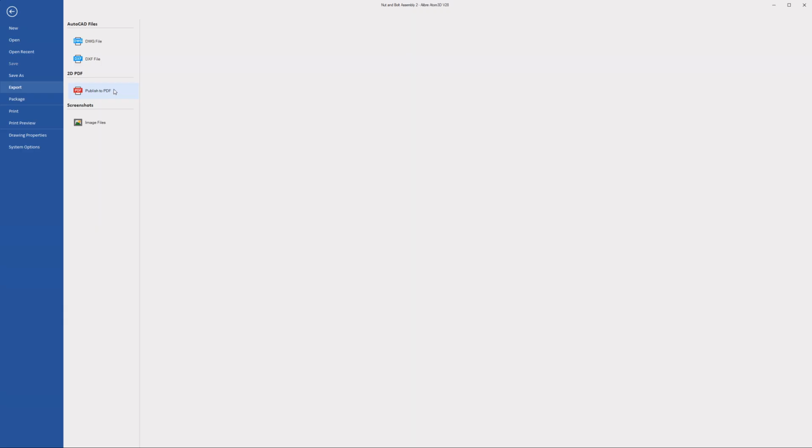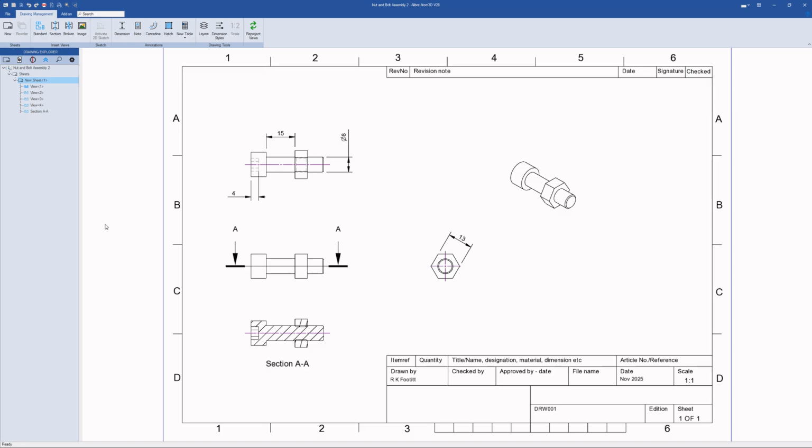However, if you're looking for a 2D view that can be manufactured against, then we also have options for AutoCAD files, either DWG or DXF, and exporting to that, you can then use those 2D drawings to directly drive things like CNC, flatbed routing tables, laser cutters, and lathes and whatnot. You can cut round profiles of parts from a 2D drawing. You can also export 3D data from part and assembly workspaces into STEP format, which is useful for CNC machining, and STL format, which is the standard used for 3D printing.